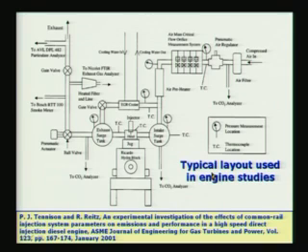In the slide we show a typical layout used in engine studies, and let me go through in some detail what it contains. This is the engine which we are now looking at. The study is basically a study of this part. Wherever TC is written, thermocouples are there to measure temperatures, and this symbol is a pressure gauge. So pressure measurement locations are also given.